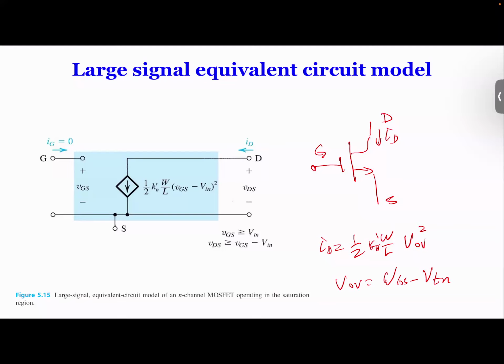Think about it. If you are given a certain VGS, your output current is fixed and has nothing to do with VDS. But if I change VGS, because VT is given, for any device once it's manufactured it's a fixed value, my current is going to change. So there's a relation between my ID and VGS. In other words, VGS is controlling how much current you have in the device. What would you call that relation? I heard somebody saying control. It's a controlled current source.